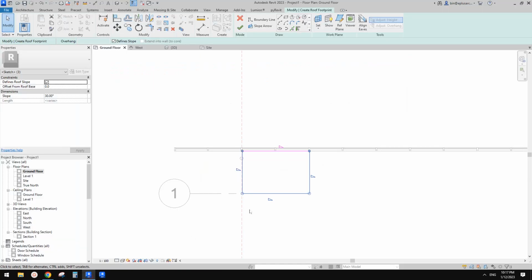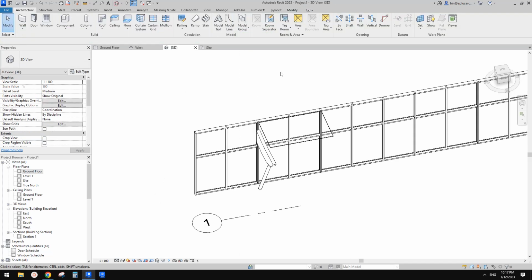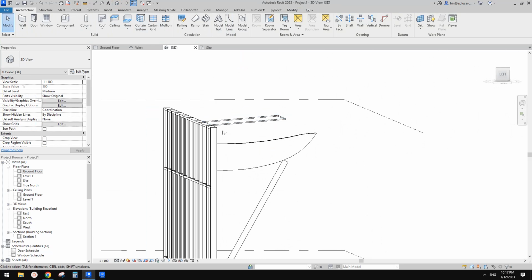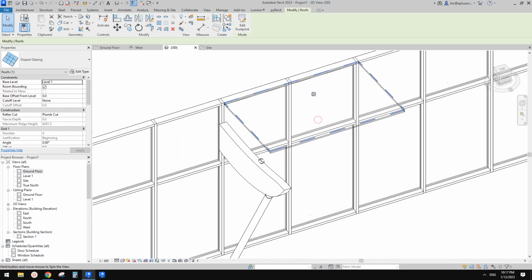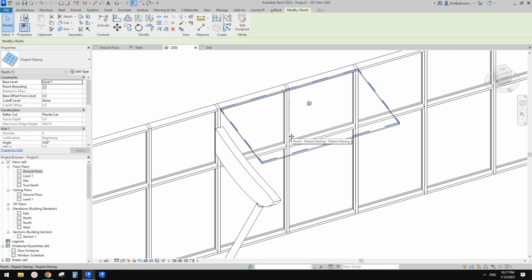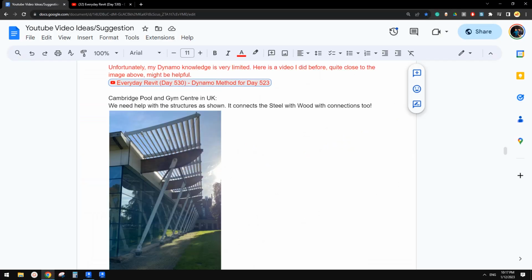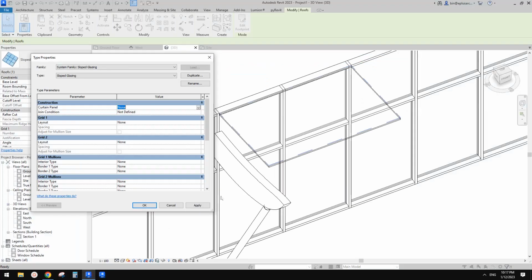With the slope, maybe from this point 4 meter. I just remove all this slope, and then I'll give it a slope, maybe 5 degrees. I'm not sure if it needs to be 5 or -5. Okay, yes, that's 5 degrees going up, and then we just need to adjust the mullions. Let's go to Edit Type first, curtain panel not defined. Oh, we need to use empty because for this one there's nothing, right? Currently there's no empty panel loaded in this project.